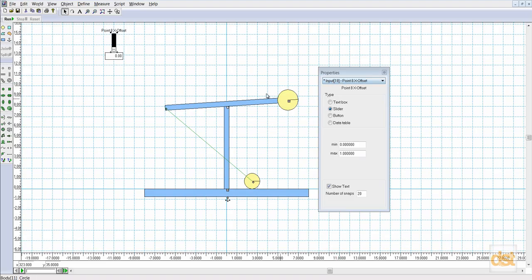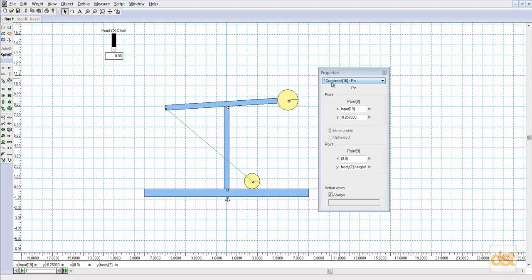That's useful for creating different slider controls and associating them with different features and elements inside of interactive physics. So if we right click, or now we can single click because this properties window is already open, notice how 0.8 now shows that the X position is controlled by this input slider right here.